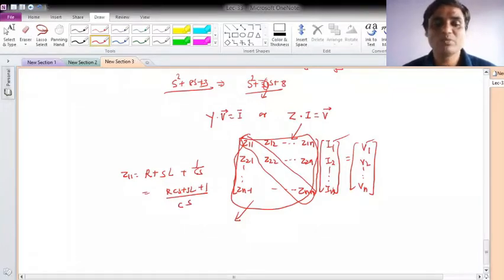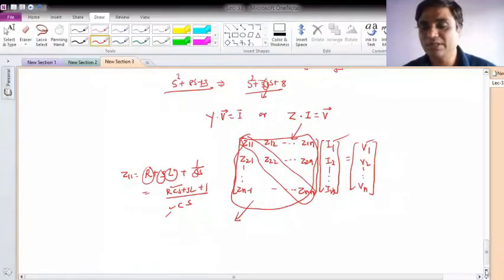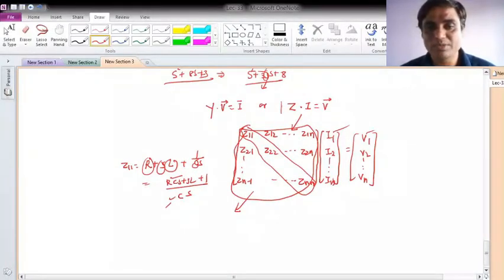And if I solve, I get a polynomial in the numerator and a polynomial in the denominator. So this will always be rational, and also these will be finite polynomials, and the values of R, L and C will always be real. So there is no question of an imaginary value of the component. That's why the network function will always be real for circuit theory applications, if I specify the problem this way.